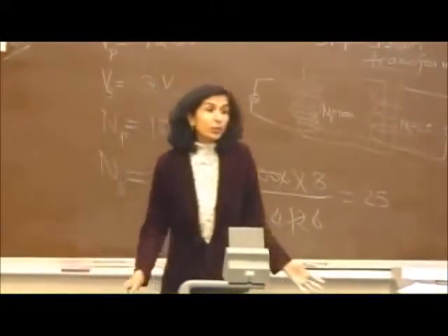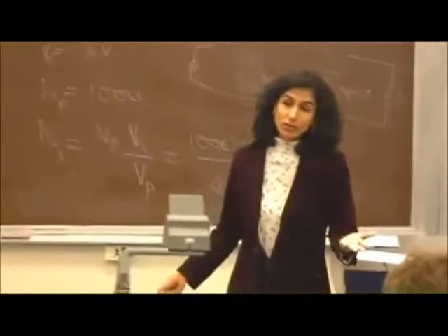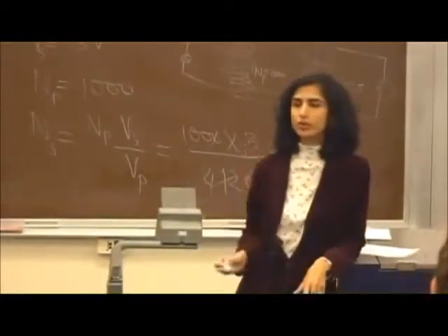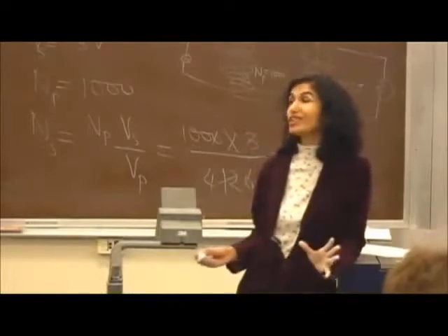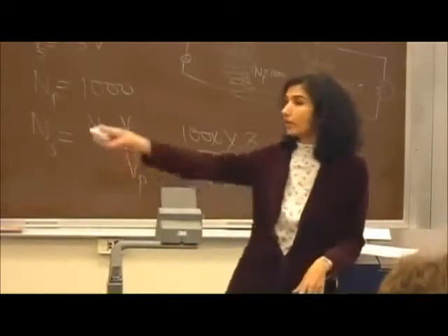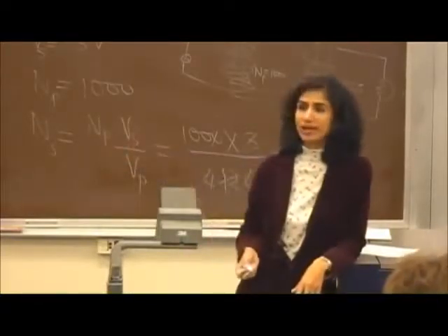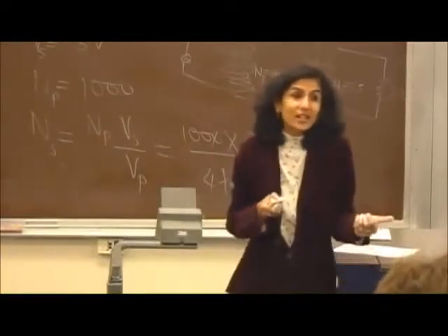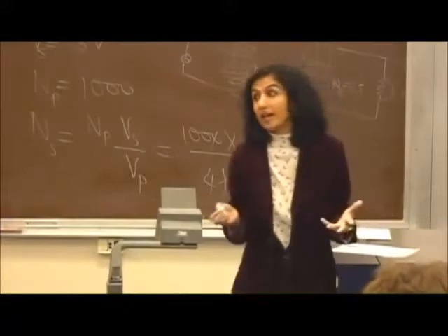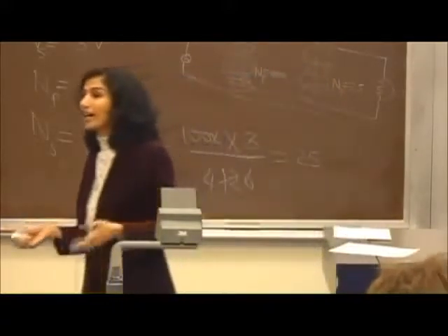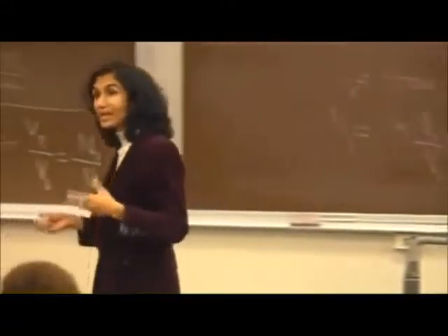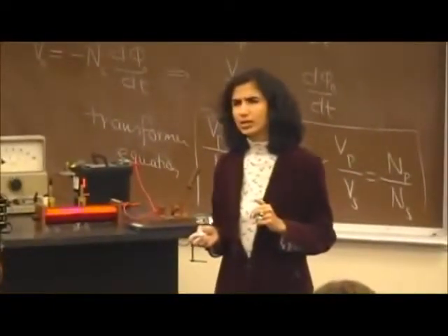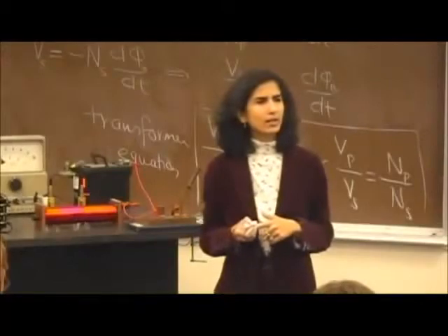On the other hand, suppose there is a transformer used in the electron gun in your TV, and that's also built into your TV, that is trying to increase the voltage to thousands of volts from the 120 volts that's coming from your power line. In that case, should the transformer have more turns in the secondary, the output side? Yeah. That kind of transformer will be called a step up transformer because it steps up the voltage. Is that making sense, folks? Any questions about that?